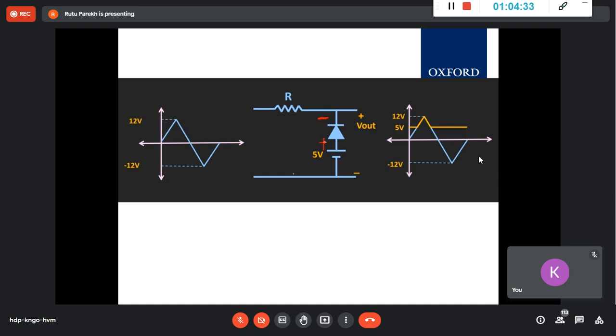In case of a non-ideal diode, if this is 0.1 and this is 0.8, it will conduct, with the 0.7 drop. So this potential has to be more than this to conduct. Positive has to be higher. In case of an ideal diode, even if it is 0 and 0.1 volt, it will conduct. So just a difference above 0, it will start conducting.